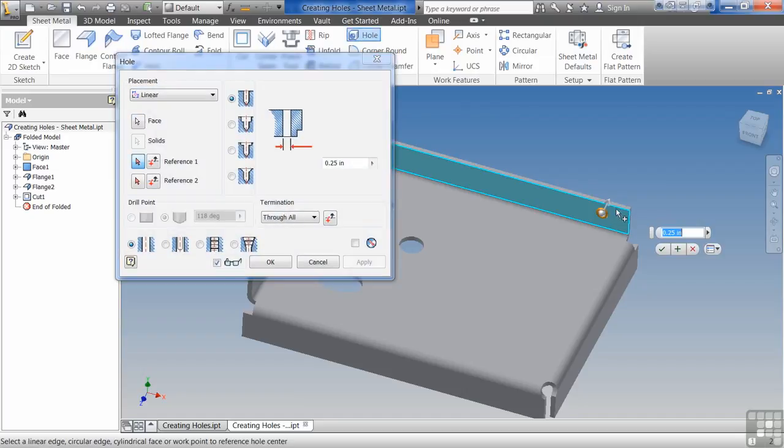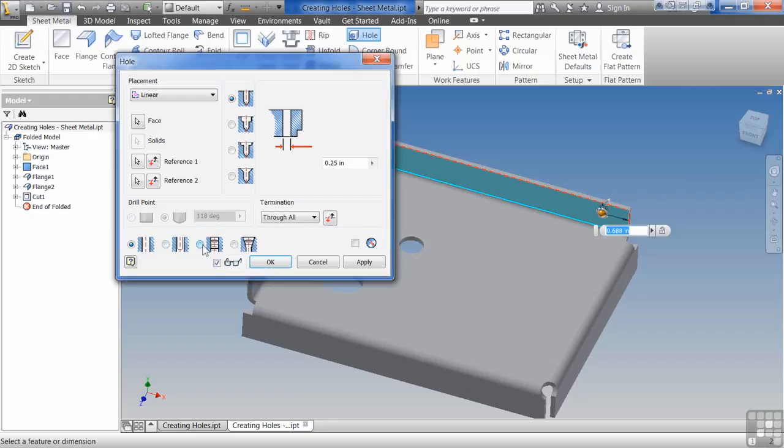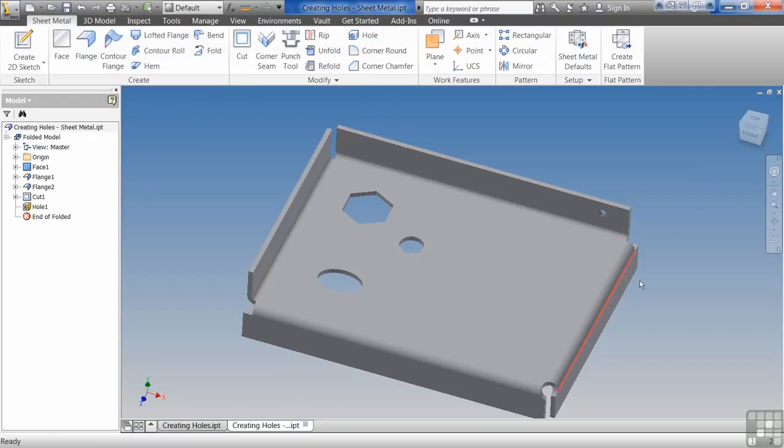For example, if I come in here and I put a hole in here, and I put this information in here, and it's actually a threaded hole, whenever I go to dimension this on the drawing, I can click on the hole and it'll say this is a hole with this size threads. Whereas a cut in a sheet metal isn't going to understand that it's a hole. It's going to understand that it's an opening. It's a subtle difference, but the reason I mention that to you is because I encourage you to use the actual hole command whenever possible.